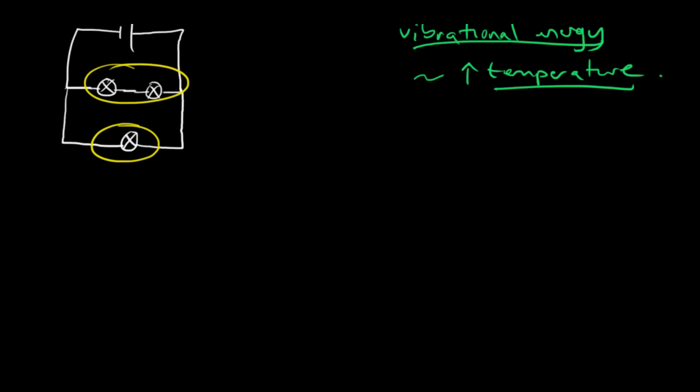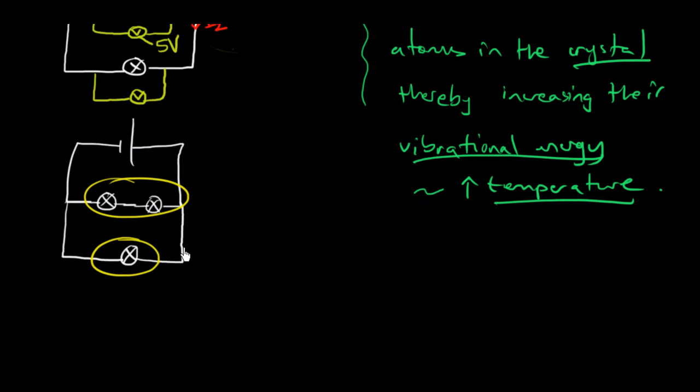And what I've drawn here, what we did yesterday, is we connected 2 in series to 1 in parallel, and what we noticed was that the brightness of these 2 was lower than this one here. It's a lot lower, and the reason for that has been explained in the previous one, but I'll just go through it quickly again. If your current is going through the circuit, you have a total I here. If these 3 bulbs are all identical, what's going on is that the total resistance of this branch, you should know the resistances in series, you just add them, so let's call the resistance of each bulb R. The resistance then of this first branch is 2R, and the resistance of this second branch is 1R.